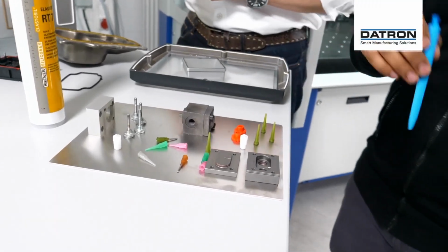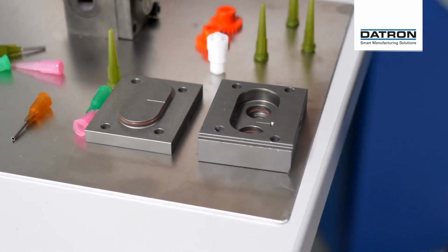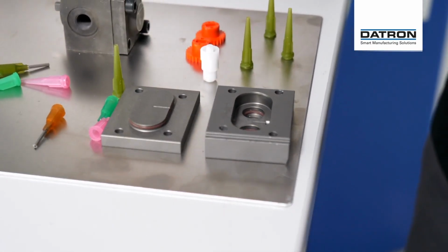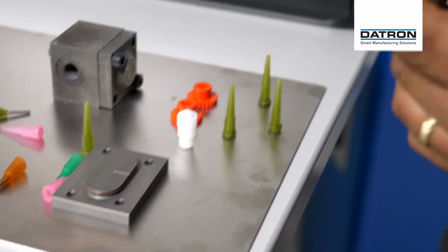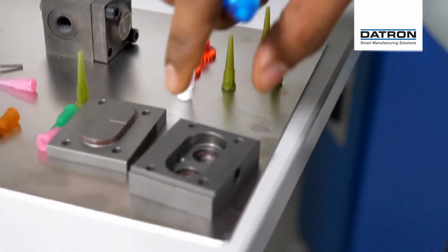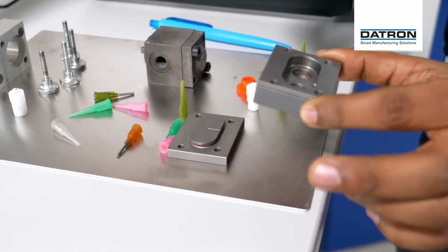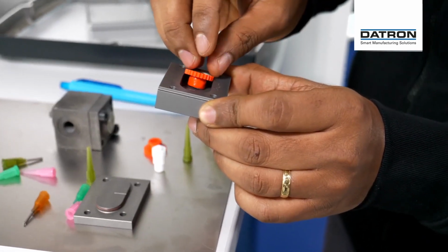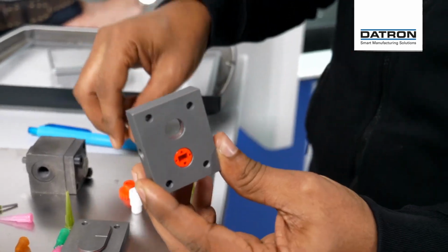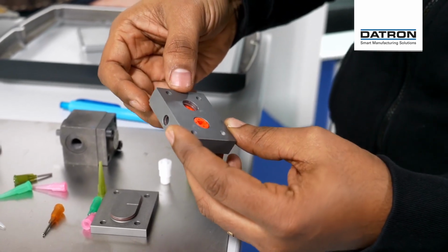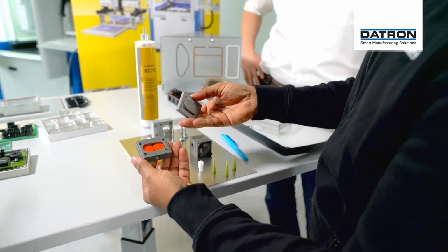So we prepared our gear pumps here. Generally we have different kinds of pumps, and which kind we choose depends on your material and application. Today we use this gear wheel pump from DATRON. This is the aluminum cover, and inside we place two gears. The gears can be placed like this. This is number 1, and then the second one. So the gears are in position now.